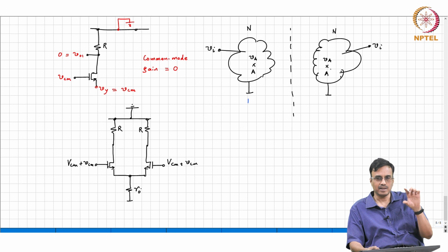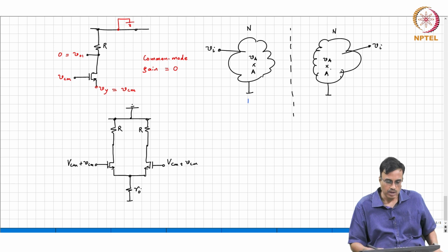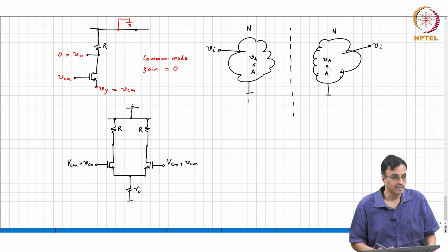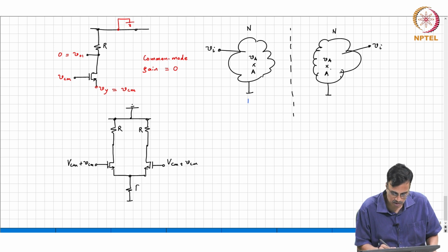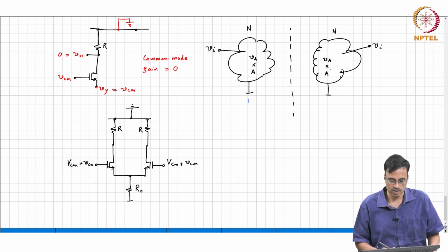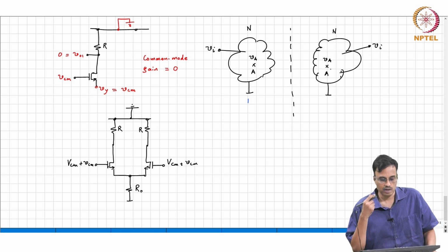What will we replace that single transistor by? Yeah, you have to use a cascode current source, which increases the output resistance by a factor of gm r0. Anyway, whatever that output resistance is, it is okay. Let us call that capital RO, appropriately.